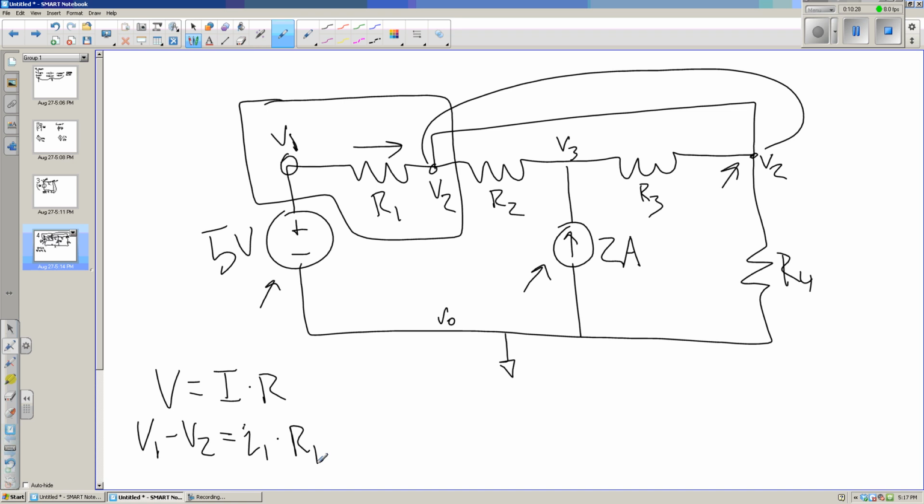So we've taken a differential, again not relative, and multiplied them, stuck them into our V equals IR, and voila, we can now start solving these. You get all of these nodes going, put up equations for each of them, and eventually you'll have enough equations to solve for each of the variables.